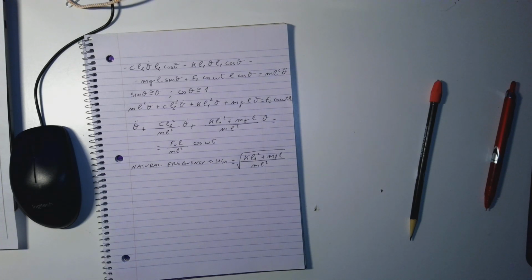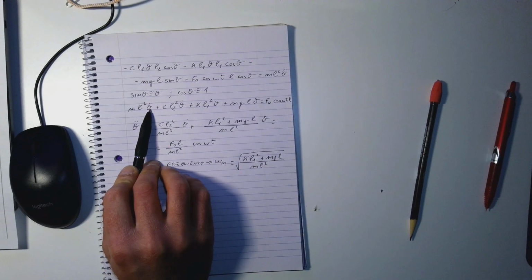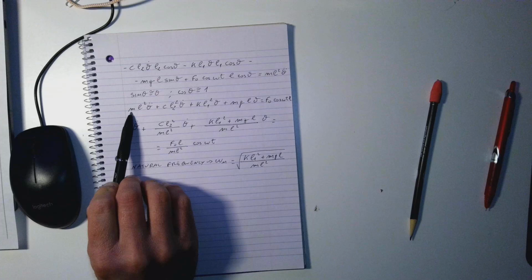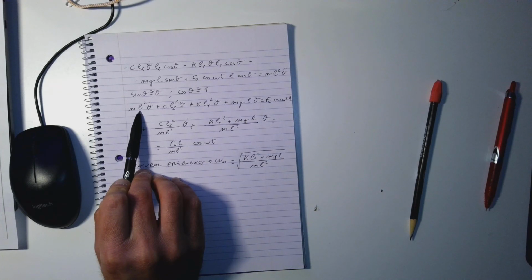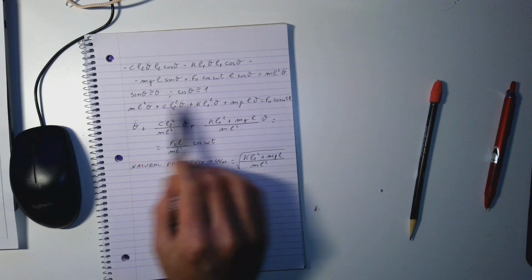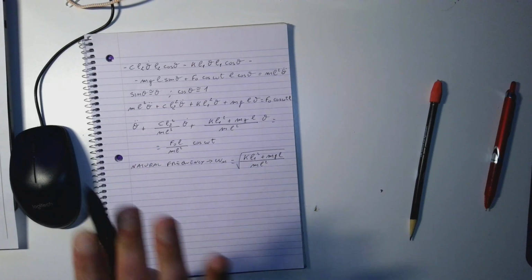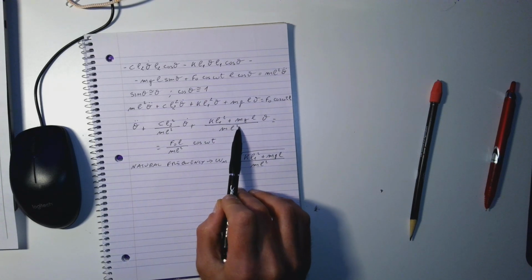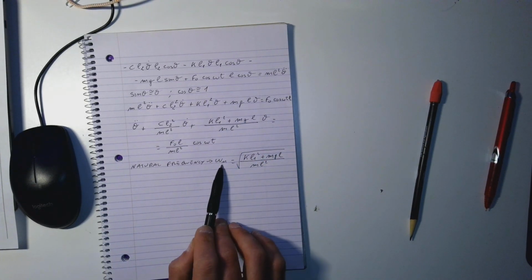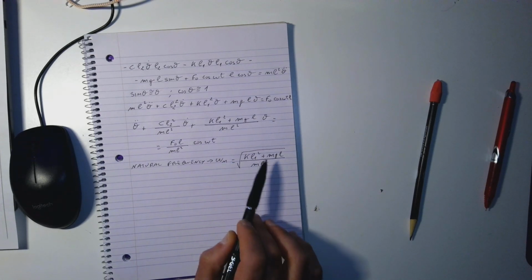Remember that when we want to see the equation in the standard form, we have to divide all the terms of the equation by the coefficient of the theta double dot, which means in this case I didn't divide simply by the mass, but I divided by ml squared. And then when I divide all of them by ml squared, so this theta is alone, then this term is finally the square of the natural frequency, which means natural frequency is the square root of this term here.